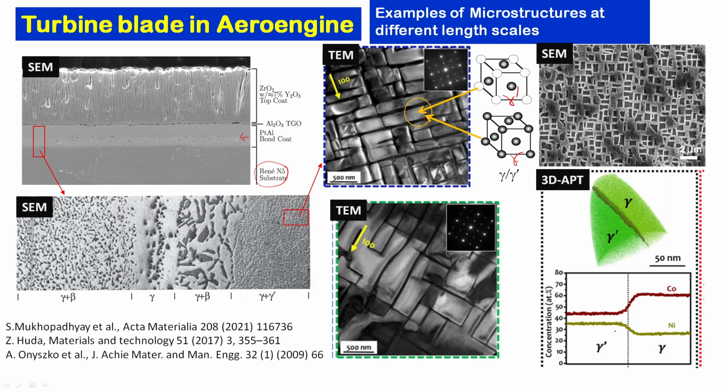So, nickel is partitioning between gamma prime and gamma. Gamma prime will contain more nickel, it has a Ni3Al structure, so it must contain more nickel than the gamma. Gamma is a random FCC structure, but on the other hand cobalt is more in gamma, less in gamma prime. One can do all kinds of analysis, I am not showing everything.